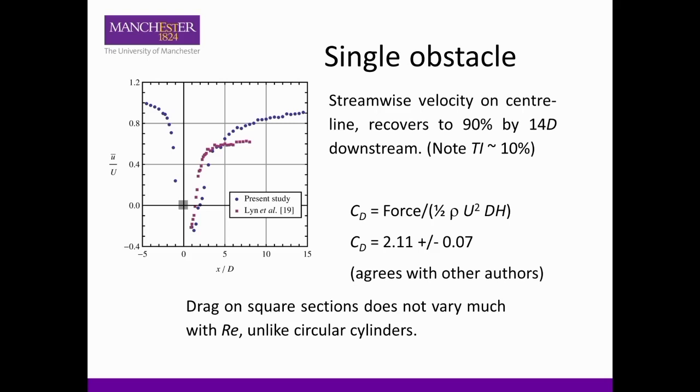This is from Lin et al., a little while ago. I would be worried that their speed doesn't actually recover to the background, anything like the background case. I should say our tank has quite high turbulent intensities, which is more realistic for environmental flows. Lots of people spend ages making really nice, clean experiments, but actually if you're modeling flows looking at marine current turbines or flow past vegetation or things like that, you actually want quite high turbulence intensities, and of course that affects the way the wakes recover to some extent.